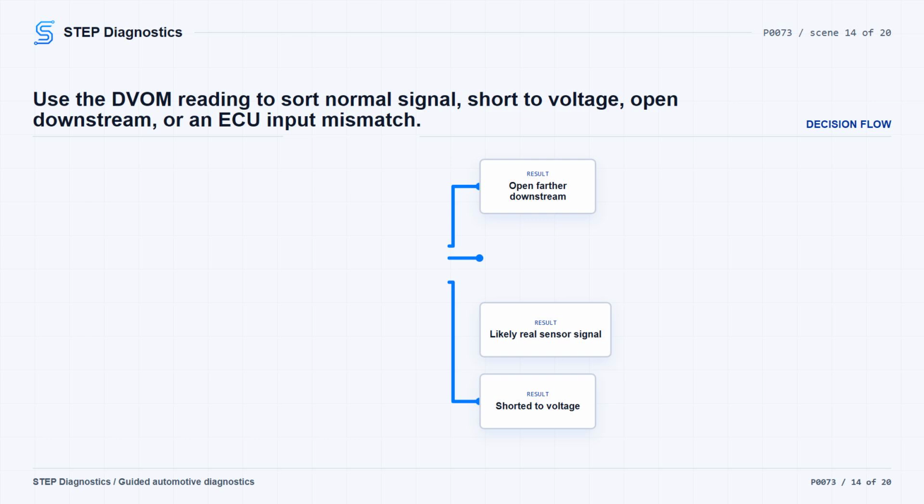For the circuit low isolation branch in this same circuit family, disconnect the temp sensor harness connector while watching for the circuit high fault to become active on the scan tool. That quickly eliminates the temp sensor as a possible cause with an active circuit low fault. If the circuit high fault does not become active, disconnect the ECU harness connector to isolate the circuit. Then check the temp signal circuit for continuity to both chassis ground and the sensor ground circuit.